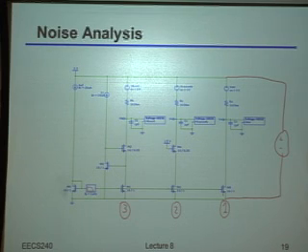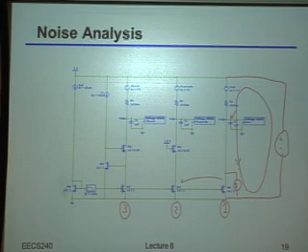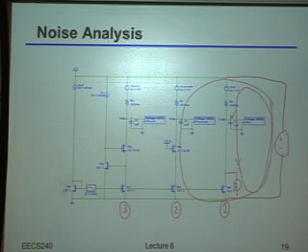If I look at, for example, the noise current from my original common source or uncascoded structure, then in order for it to create a noise voltage at the output that we measure, that current has to flow through that loop like this, right? In other words, it has to actually flow through that output resistance. Well, if I look at the noise current from the same transistor in the cascoded structure, indeed, most of that noise current should actually flow through the loop that includes that resistance, right?